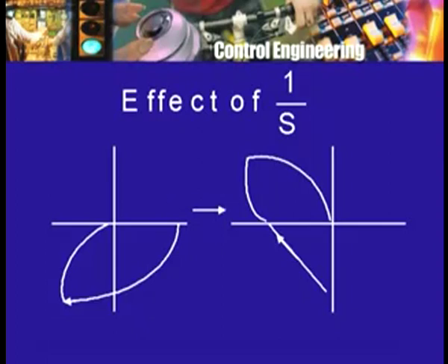From this we went to this. Now, as a result, this plot is crossing the negative real axis, that is, at some frequency the phase shift is becoming 180 degrees, and therefore we can be in the danger zone, because if the gain corresponding to this is 1 or more, then the point minus 1 plus j0 may turn out to be inside the overall contour gamma prime. Of course, it is too soon to say anything, because I have to complete the whole contour, then only I can draw any conclusions.